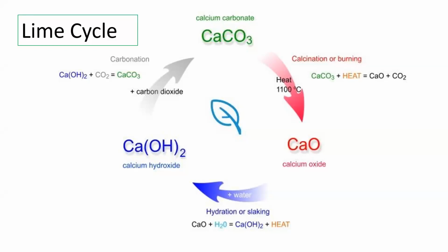So in the calcining process, the carbon dioxide is driven off along with a great deal of heat. And that produces calcium oxide, which is highly volatile. It's stabilized by adding water to it. So you have calcium hydroxide, and it comes in powdered bags, and that's what we use to surround the hemp hurd with.